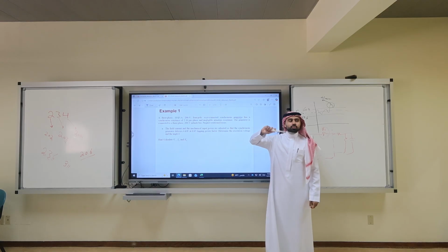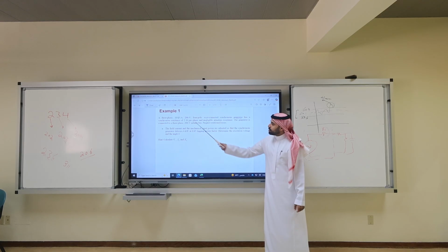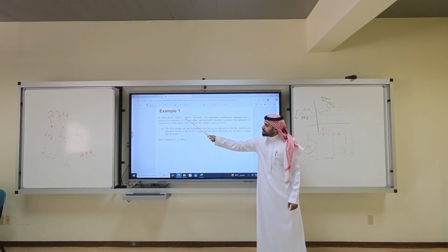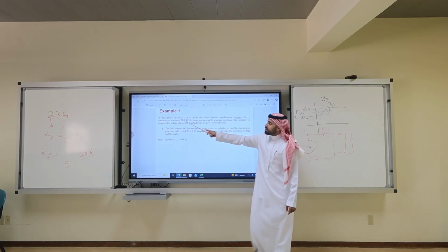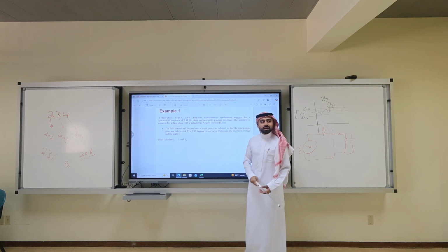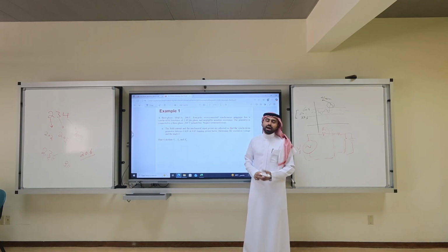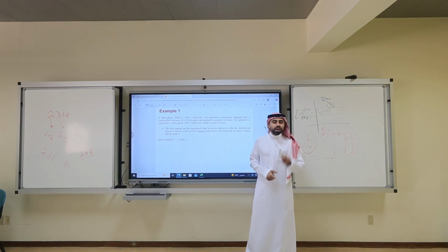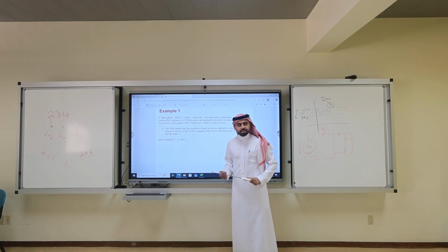Is it rated or non-rated? Rated. It is rated for load by design. 208: is it line to line or phase? Who said phase? Wrong, because this is a three-phase machine. Do we market a three-phase device with phase quantities? You never market a three-phase power device with anything but line to line. We love line to line. We never market any three-phase device with a phase quantity because that doesn't make any sense.